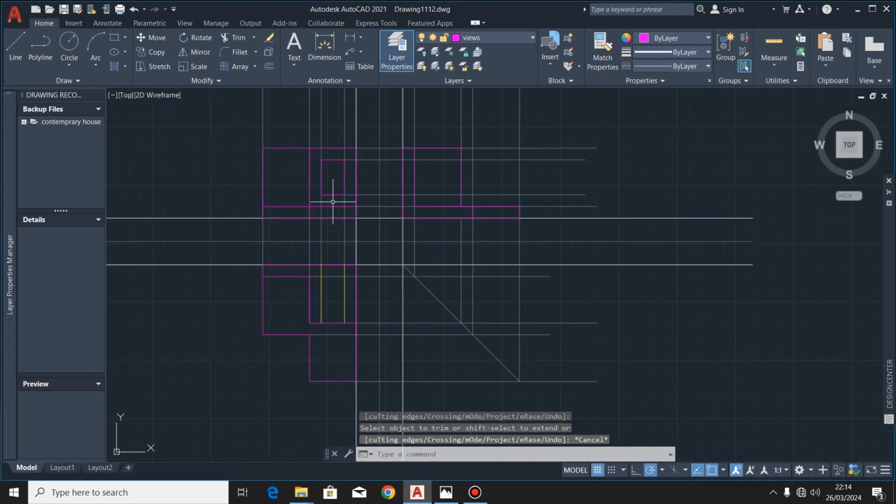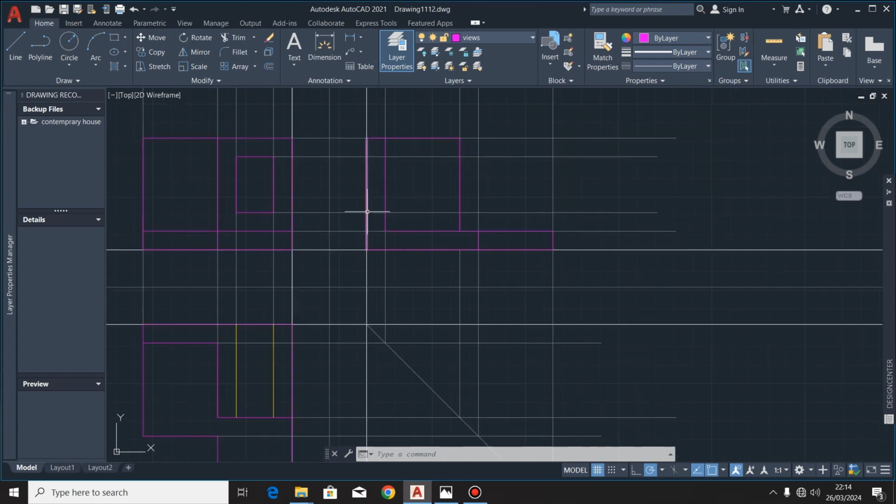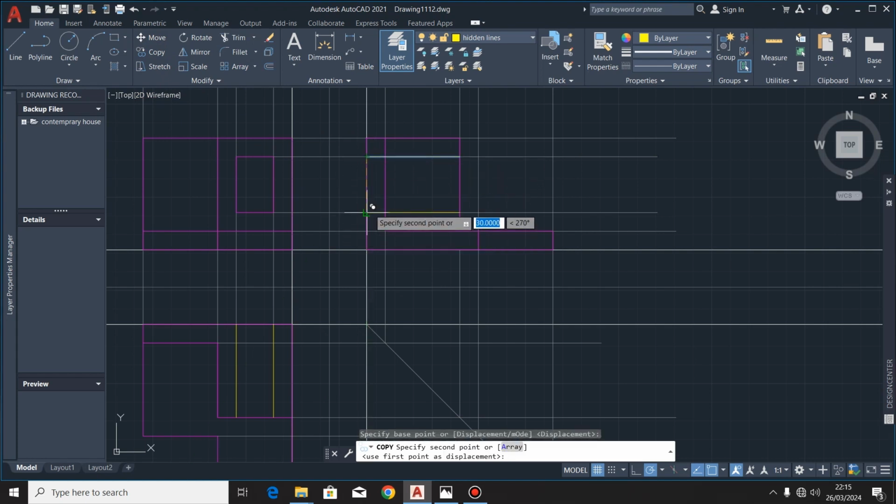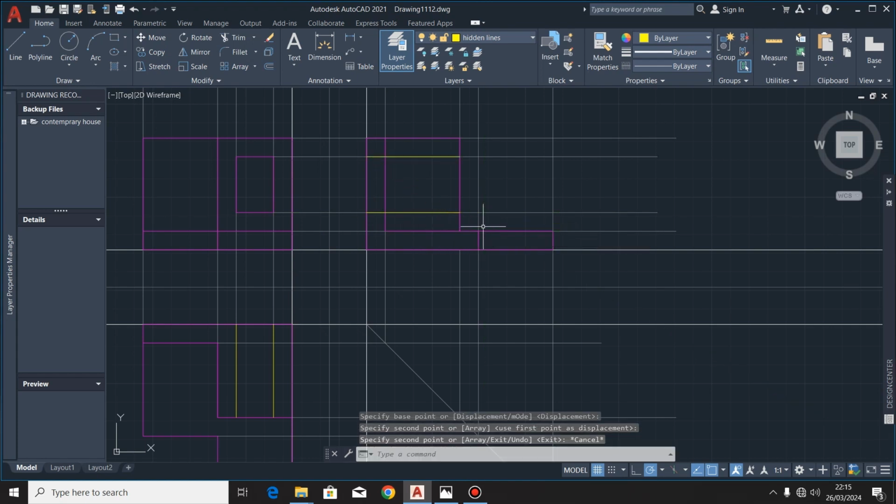What we are left with is to indicate this rectangular hole as hidden. Remember, it runs from this edge up to this edge. The same thing applies to this upper edge. So I'll activate my layer for hidden lines. I'll use the line command. Then I'll draw a line from this point up to that point. Then after, I'll just copy it to that point. Then I press escape.